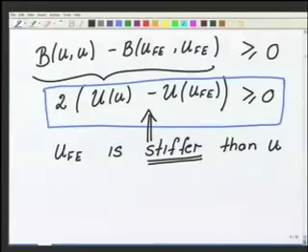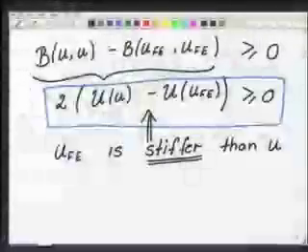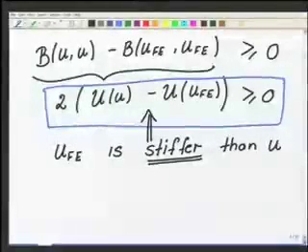than U. Okay. One thing we should keep in mind is that all this could be done provided the UFE satisfies the homogeneous boundary condition. That is, this is only true for problems where the geometric constraints are homogeneous in nature. If they are not, you cannot say anything about that problem. Okay. So we know that the finite element solution is stiffer. In what sense? That is, the strain energy due to the finite element solution is always lesser than that of the exact solution. So this could be a very good check for the finite element program that one writes.